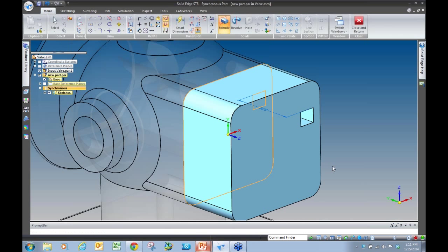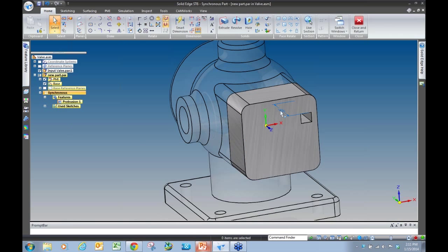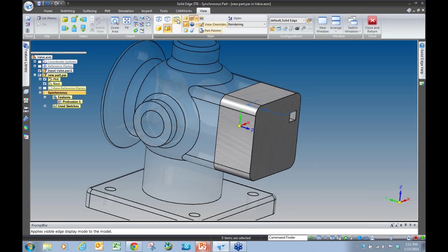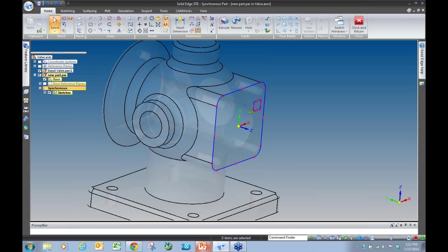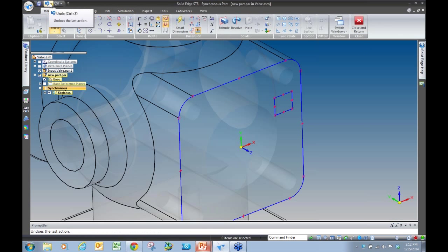I can also use the Include, the Project Sketch, and get this entire face over here if I needed to. Accept that, and I can start clicking over using Synchronous in my steering wheel. Go ahead and start building my new part off of here, going off from there. And I didn't have to use an inner part copy. This is just a part that I built off of that by using the new commands that were allotted over here in my tools area.